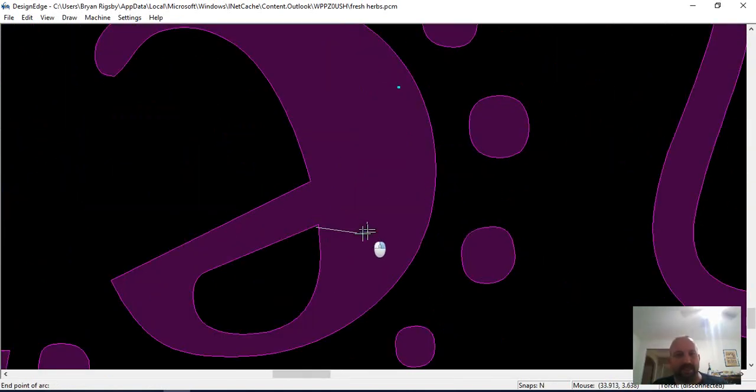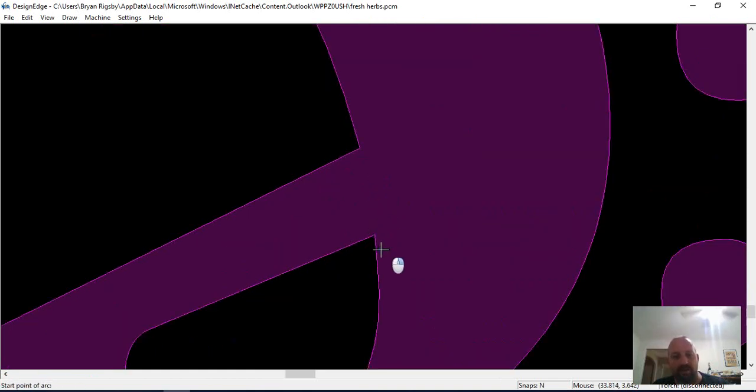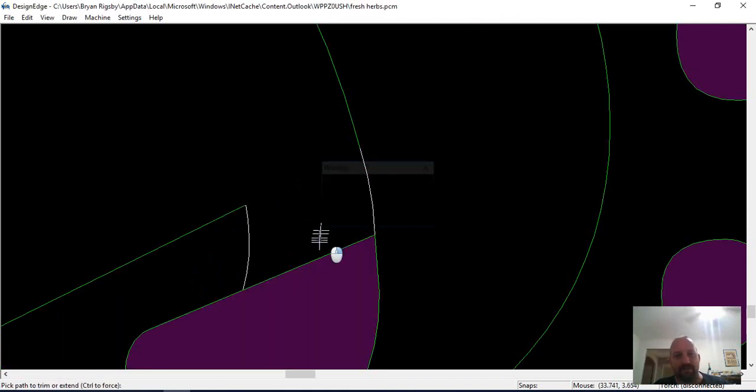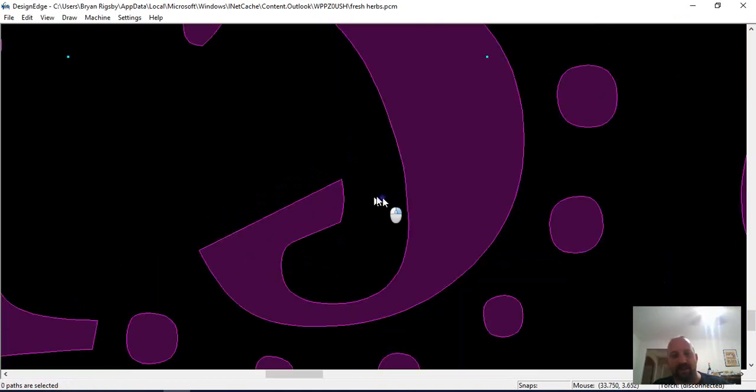Z from the end node point, missed it, to the end node point. And I'm going to try harder to click on what I want. Oh, I see the problem. I bumped my end button. Turned on my node point snap, so when I pushed in, I was turning the node point snap off. Okay, offset 0.15, enter, hold control, jumps it over, X, all that out, and J for link it or join it.